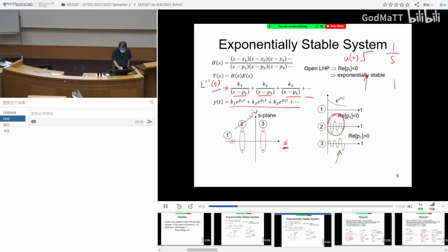So if sigma is negative, which is this, you always have a negative real part. And therefore, you either get this or you get this. A system that, after you excite it using a Dirac delta function, goes down to 0. That system is stable, right? No matter how you excite it, it doesn't stay long. Eventually it will decay and go back to 0. This system is stable. But if you excite it, it grows exponentially. Of course, it will not go to infinity. So it grows exponentially, eventually it will saturate. This is oscillator behavior.